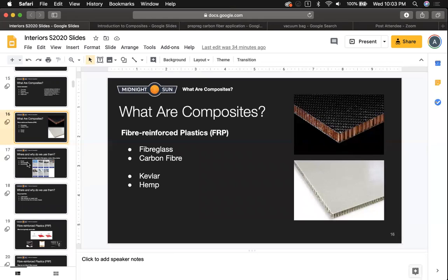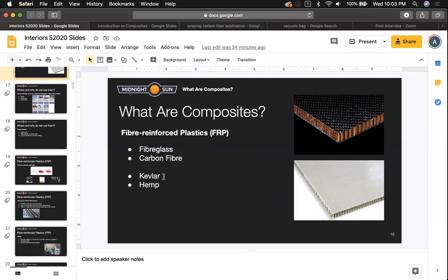So I guess in terms of catamaran cover, if we're needing stiffness, it's adding the right amount of core in the right areas such that it's stiffer where it needs to be stiff. And the nice thing about composites is that you don't necessarily need to make the entire thing uniformly thick. You can only put core where you need it and use a thinner core or less core somewhere else, where it's easier to fit into a corner, where it might be hard to get a really thick core to follow a really tight corner.